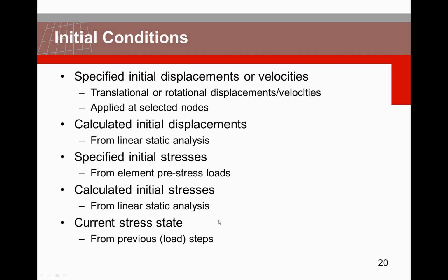You can use pre-stress loads as initial condition. You can also calculate your initial stresses from a linear static load, or you can take up the current stress state from previous loads, for instance in a combination with static analysis. So in case you first are going to build your bridge, so you have your stresses from the construction process, or your dam, or you want to take into account certain temperature conditions which yield to a specific stress state, you can use that as a starting point for your dynamic analysis.